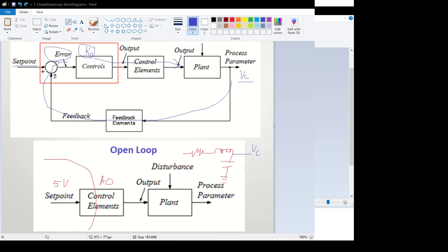Okay, so if we look at our tags here, I guess I'll go through the tags first. So I have my input coming in is the voltage across the capacitor, which is the channel 0 input of my analog card. Okay, so let's look at our analog card. We're using the fast analog card here for the Allen Bradley PLC.